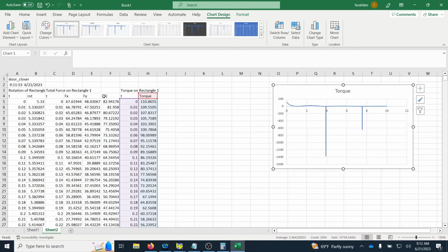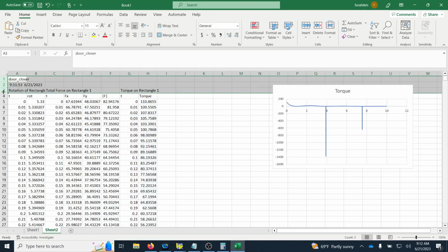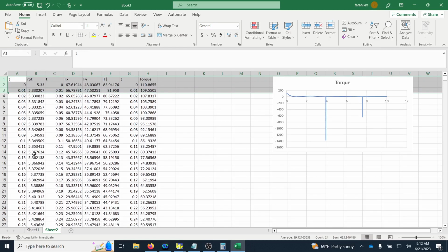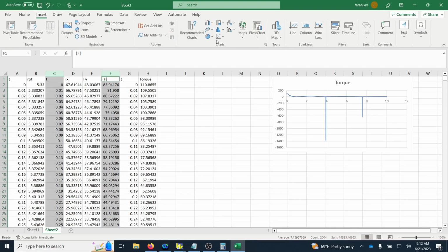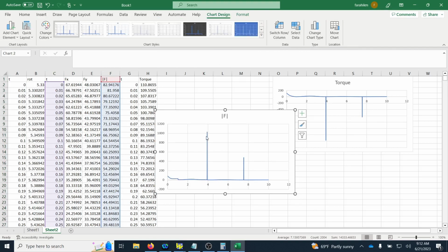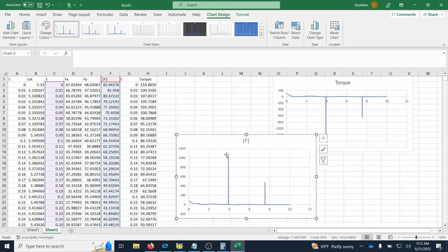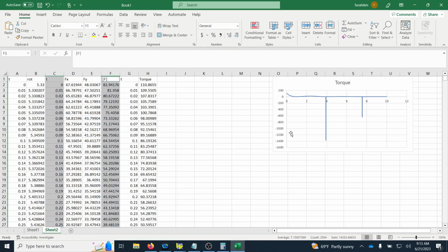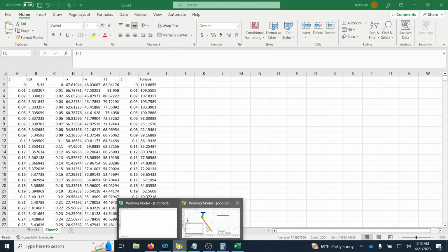So we keep having these high torques applied, and probably that applies to the force as well. So if I let me remove these 3 rows, and then I want to copy column C and column F and see the forces. Again, you can see the very high forces, it's like impulses applied to the door as it would slam to the frame. That's not something that we want in our system. So I'm going to delete these. And so we saw what happens in that case.